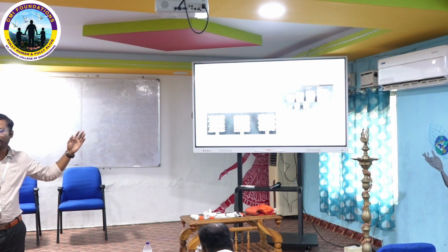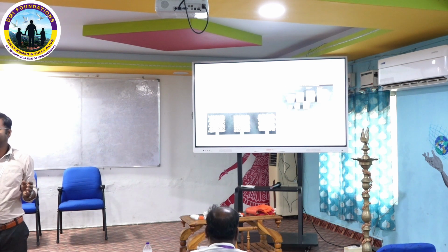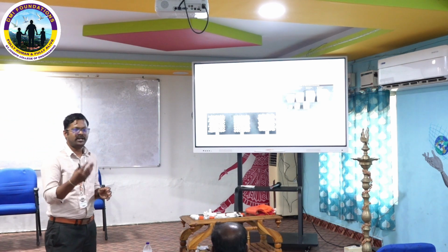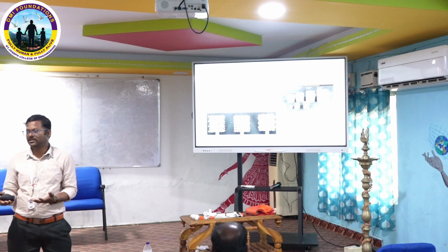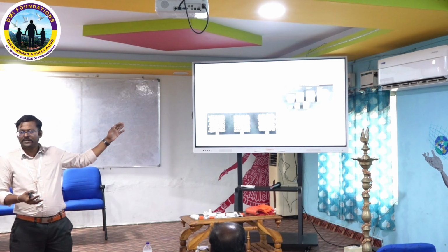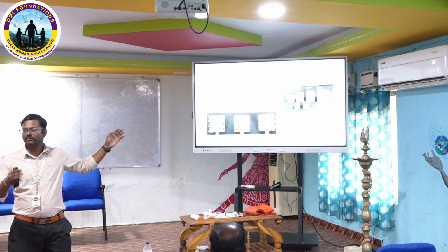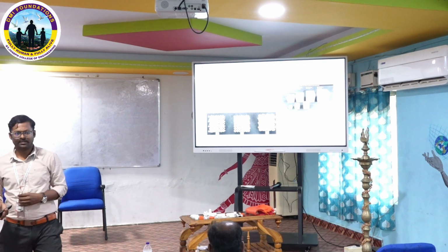You should use 10 to 20 or 30%, maximum 30 to 40% of relative density. Above that, it will act as a solid structure. So if relative density is 70%, the structural property gets demolished, and the material properties will be more.